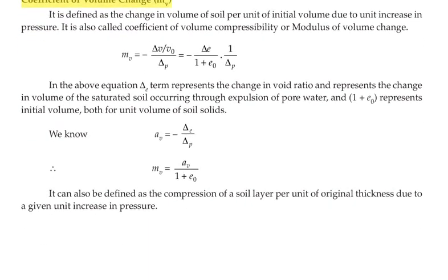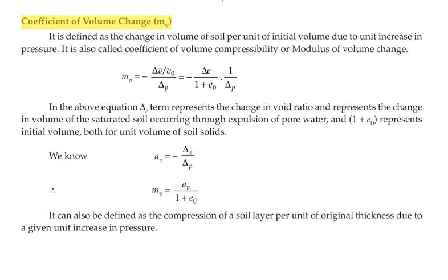We already know AV is equal to minus del V divided by del P, and again the coefficient of volume change MV is equal to AV divided by 1 plus E naught.